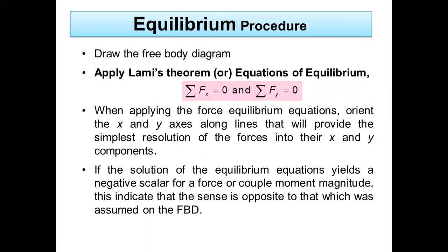Next one is how to solve the problems which you are dealing with equilibrium. The first step to solve the equilibrium is to draw the free body diagram. The very first point is to draw the free body diagram. Next, check for Lami's theorem, whether the particular problem is dealing with Lami's theorem or not. How to check Lami's theorem?